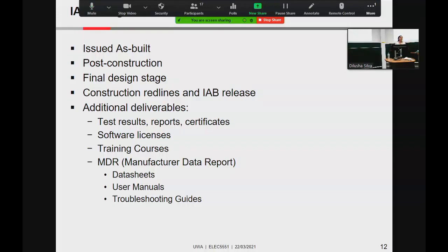Drafting team, then you assign based on the schedule, if it's urgent or whatever, whenever it's assigned. Then the same drawings of your design are redrawn, but with the changes that were done in the red lines. And then you stamp that with as-built, and the design goes out. That's it. That's your engineering design life cycle in an EPC contract.